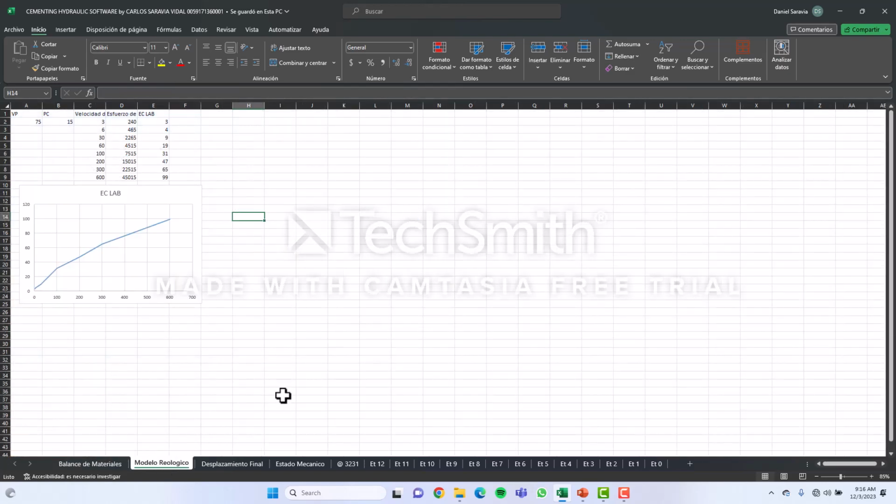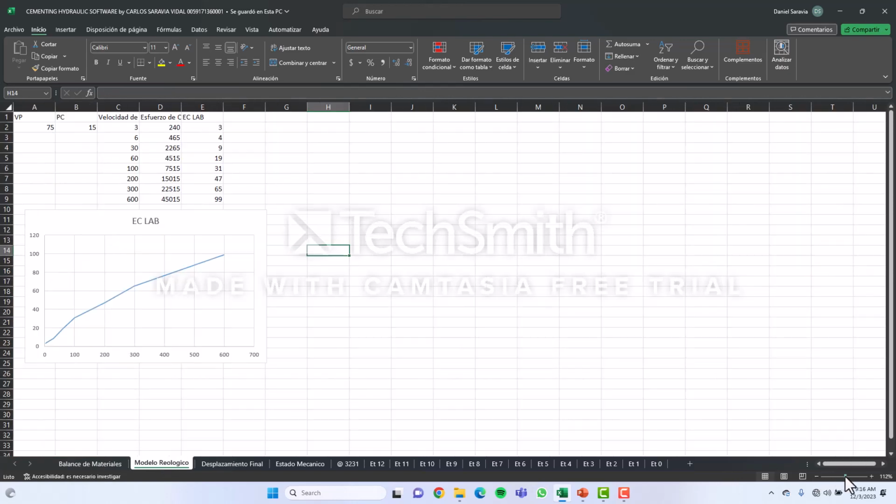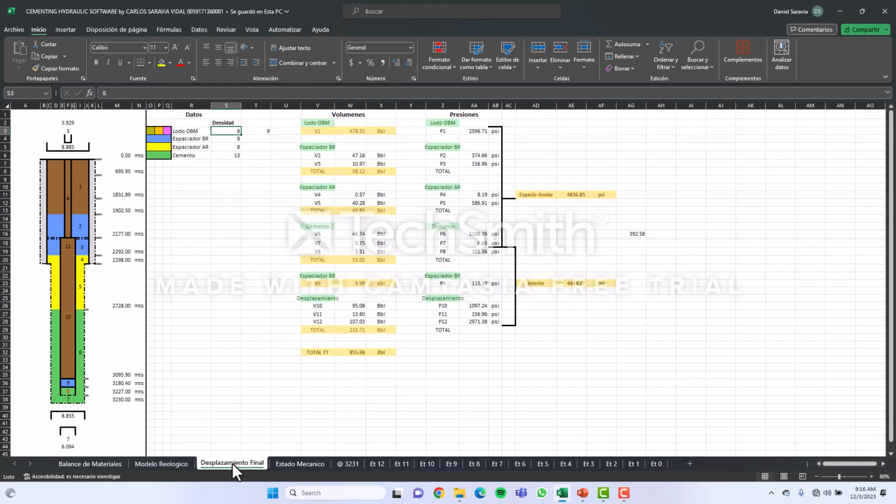And also, we have the rheology for each fluid, okay? That you can also check in your laboratory when you have the availability to check the values. This is the well schematic. This is an HPHT well, as I mentioned. The depth is in meters. You can see here it is around 3,400 meters of measured depth, and the inclination is an average of 16 degrees.